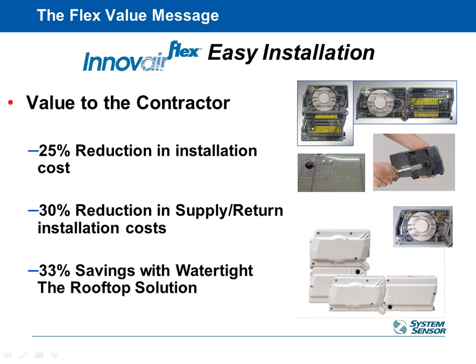Installation costs in general have been less than other products that we've used in the past, mainly because of the flexibility of this system. So it is fairly easy to install. The tubes are very easy to put in. Wiring is simplified, so that does help you a little bit. It also helps you if you're going to do a supply return system. You don't have to buy 2 full detectors, you can buy one of these heads by itself. That reduces the cost a little bit more. And if you need to install one of these outdoors, the cost savings is pretty good because you don't have to retrofit a NEMA enclosure around a regular detector. This guy's already got the NEMA enclosure built in.